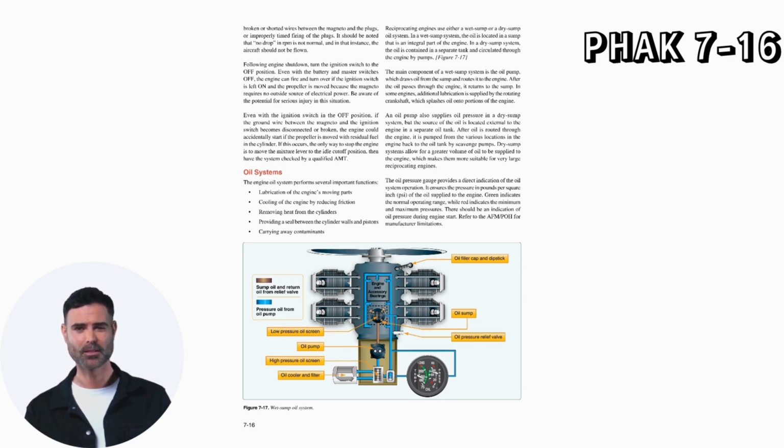Following engine shutdown, turn the ignition switch to the off position. Even with the battery and master switches off, the engine can fire and turn over if the ignition switch is left on and the propeller is moved, because the magneto requires no outside source of electrical power. Be aware of the potential for serious injury in this situation.